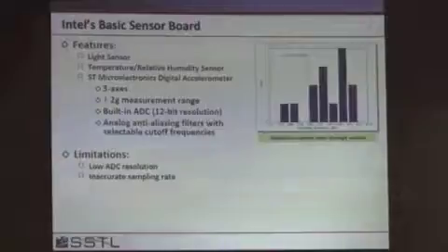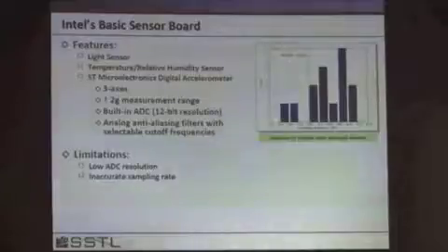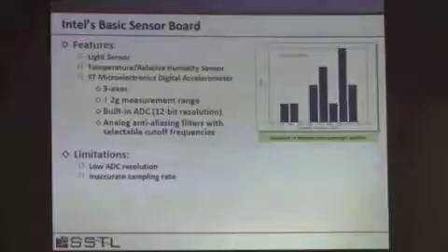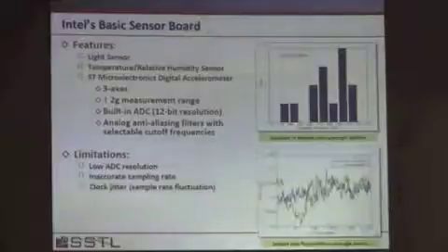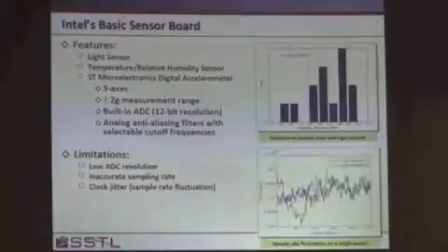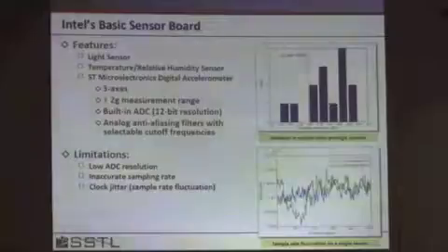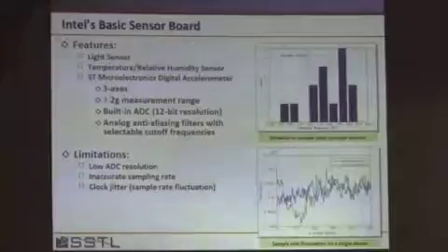So you can see here, for the sensors that we had, the 560 was the nominal sampling rate, 530 all the way up to 610 was what we got. In addition, the sampling rate wasn't constant with time, so it varied with time. So how can you use this for real structural analysis, for real investigation of the behavior of structures when your sensor isn't behaving as you expected?